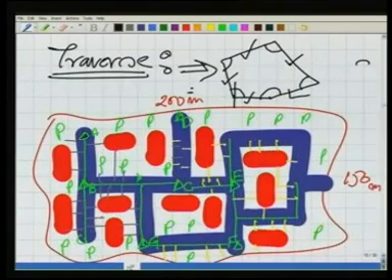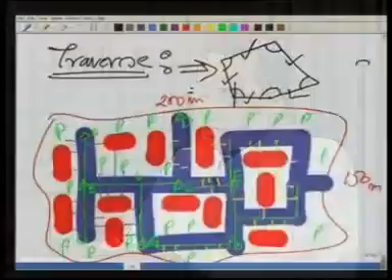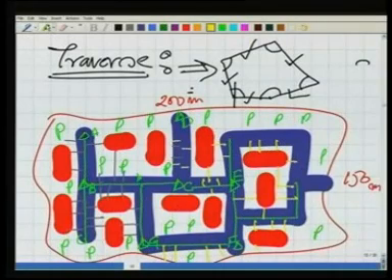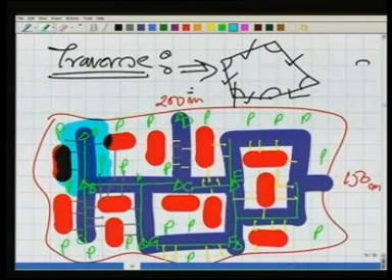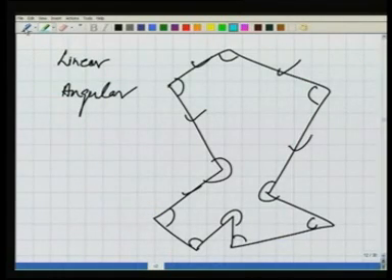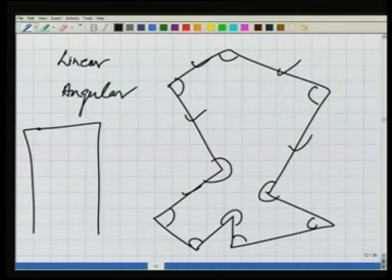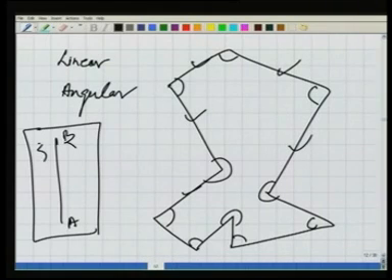Well, in this case also, in this example, can we really plot it on our sheet, on our drawing sheet? I can take it to our field book, because in taking it to the field book, what we can do, this entire area which is highlighted can be represented A, B in the field book page, one page, A and B. So the entire area is shown here, the chain edges and the offsets.